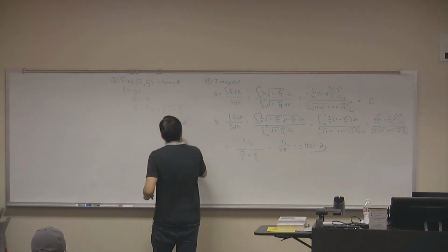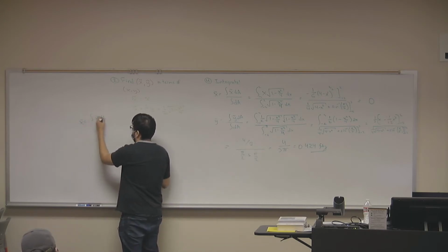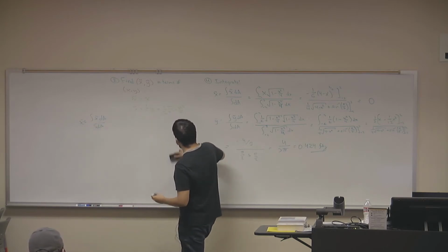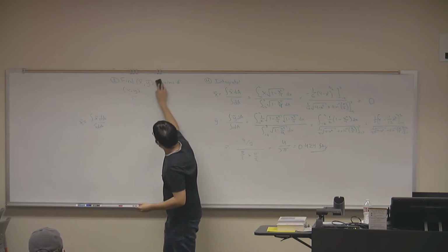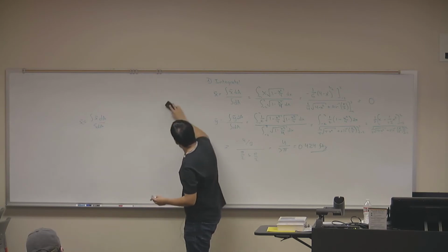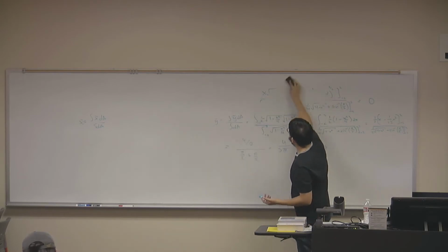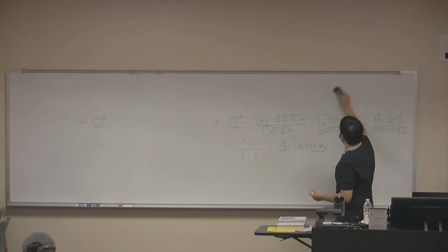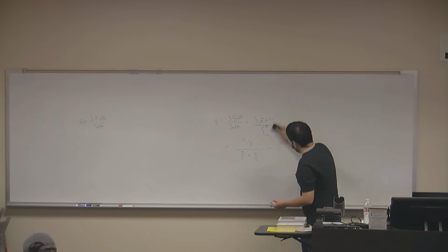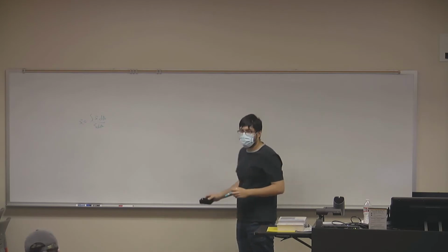I have a question. The equation that we use for the centroid, let's say in the x direction, was this one, right? That's what we just used. How would that equation change if we're using 3 dimensions? Instead of it being the derivative of the area, would it just be the volume? Exactly. Instead of dA, we would have dV, because in 3 dimensions we are dealing with volume, whereas in 2 dimensions we were dealing with area. You'll see that other than that very small change, the rest of the problem is going to be exactly the same.